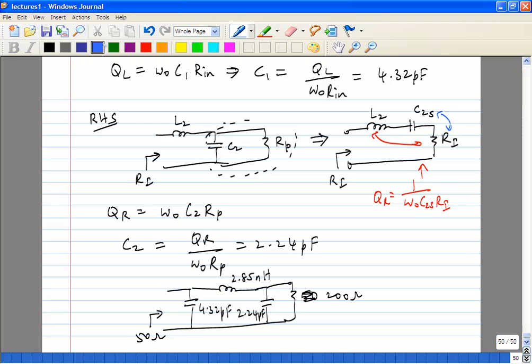So you might get a case, when you go into design an LNA or something like that, where you'll be given a band it needs to match over. I'll give you an example. Say you're designing for wireless LAN. You have a certain band, 2.405 to 2.485 gigahertz. That's your bandwidth. So your LNA in the receiver should be well matched in this band. You can't say I'm matched outside it, because then you'll be picking up stuff from other nearby bands. The advantage of having a narrower response is you get some suppression of signals out of band.